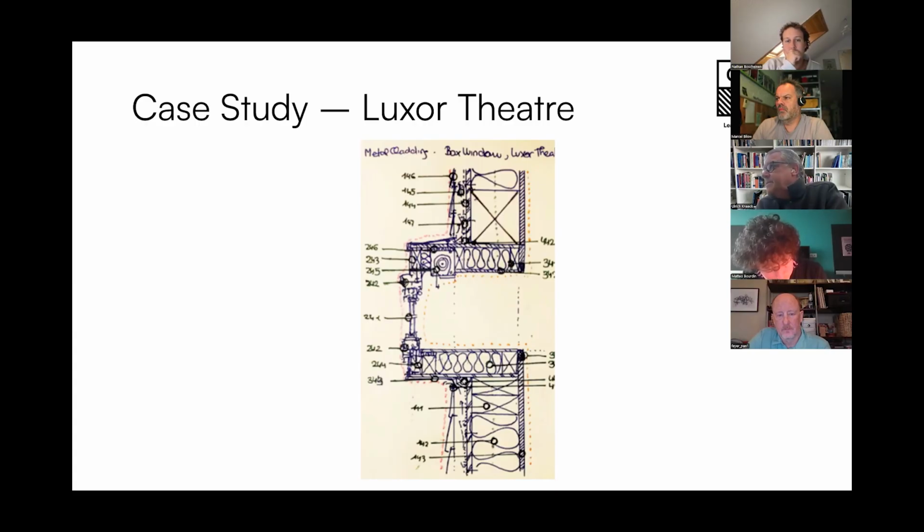Side note, if you change the dimension of insulation that intensively, you may end up with humidity in the cavity because dew point appears, and then maybe that would be a risk. But okay, having said so, we see the window being placed quite outside, but that's in principle the way I would design this as a setting. And if I'm not mistaken, we also saw some similar things with the Gehry buildings in Düsseldorf. They look very slender as boxes, but that's a design issue. They also have this insulation circling around.